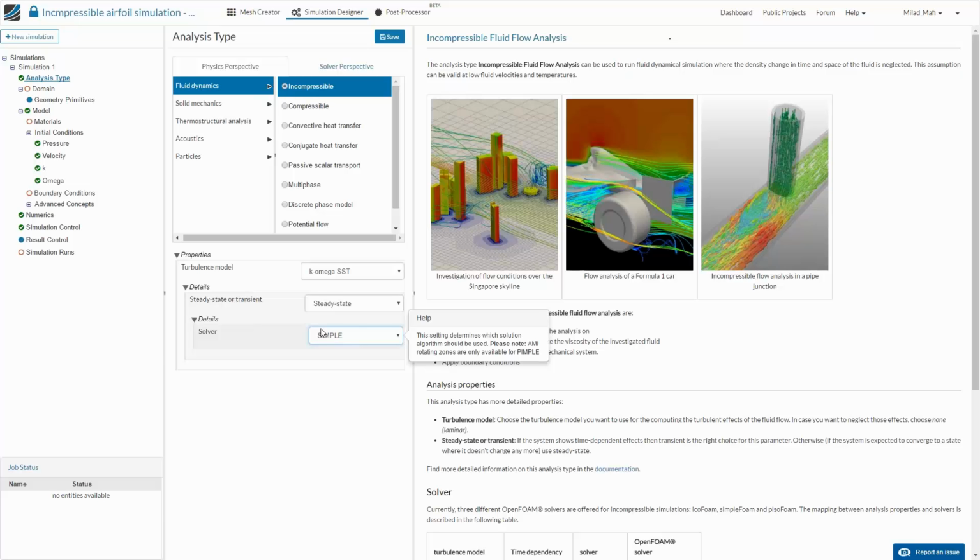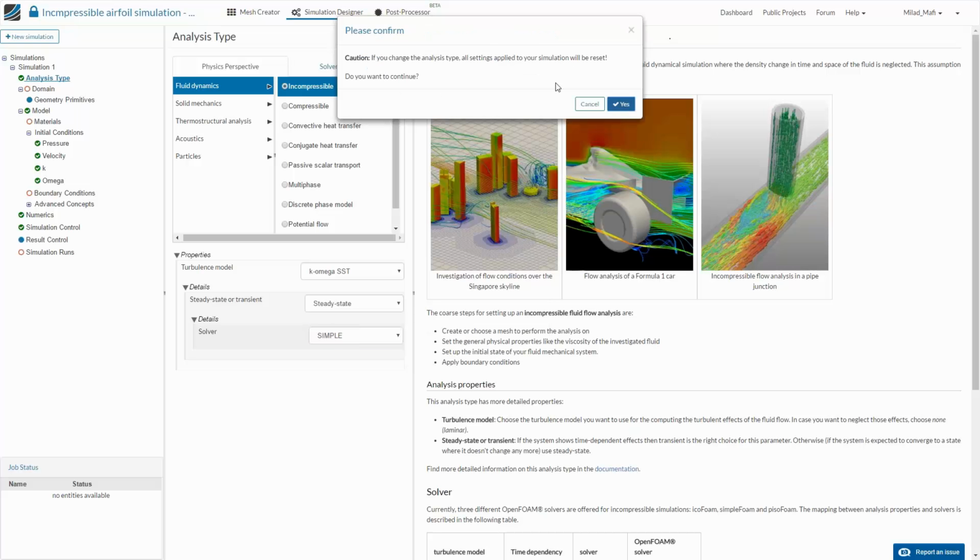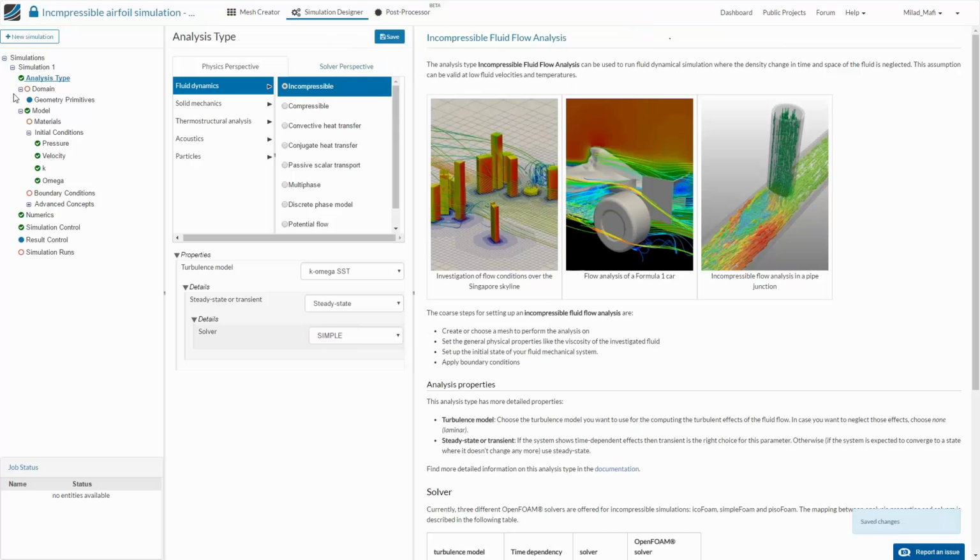As I told you, we use for every quantity a different solver. And pressure and velocity have to be linked somehow. And this linking of pressure and velocity is done over so-called pressure-velocity coupling. And this is what SIMPLE describes, a dedicated way of velocity-pressure coupling.